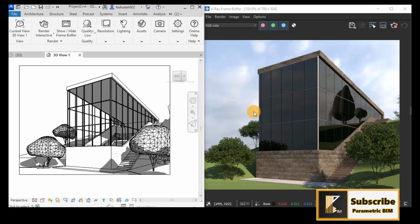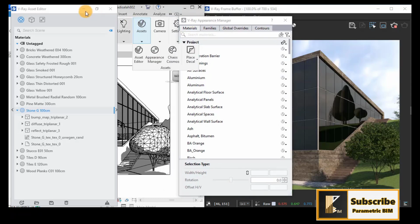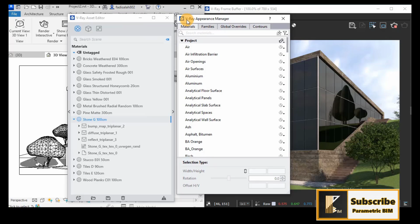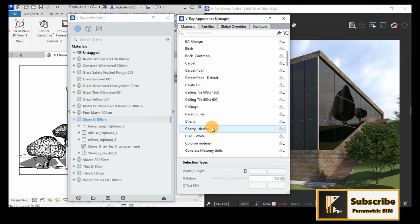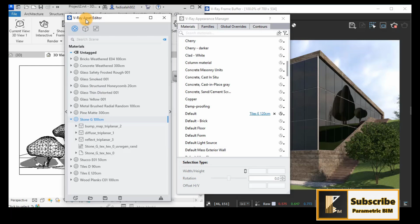So what we have to do, we have to go to the asset editor and the appearance manager. Always we have to work with these two, and we talked before about the difference between them. The appearance manager is to manage the material that we have in Revit and to replace it by the Vray material that we bring from the Vray asset editor.